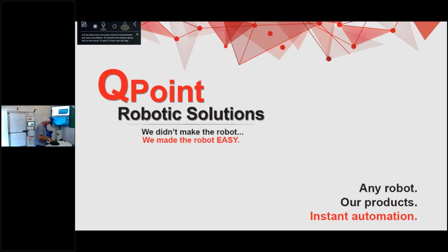I'm not quite ready to do this live for you on this system, but if this was the robot, this clips on, has the same kind of safety device as the teach pendant to make sure it's safe, and you can enable this and just drive the robot around. That allows an industrial robot to be manually driven by hand, similar to how collaborative arms are.